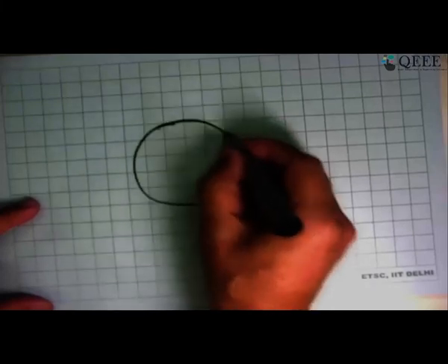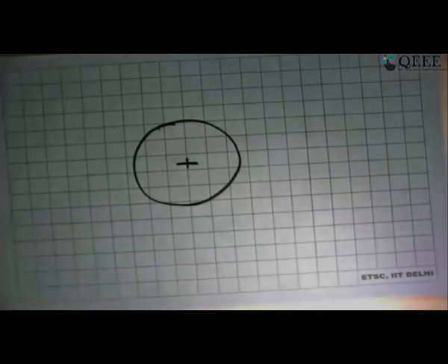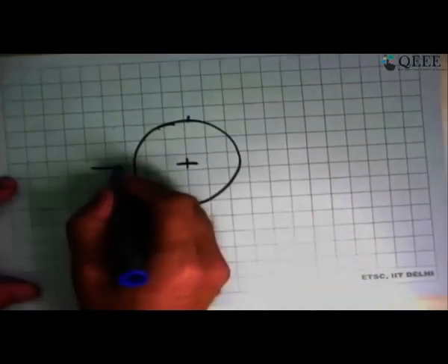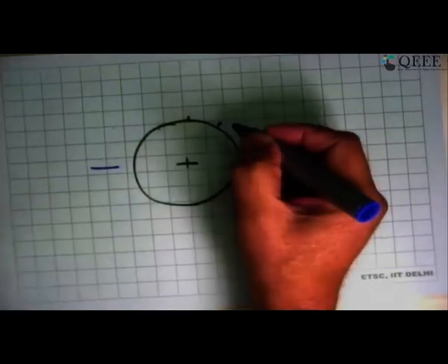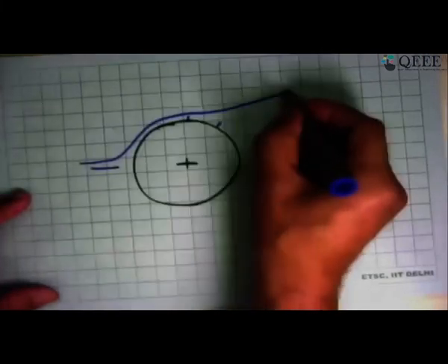Okay, the question is: is the boundary layer separation condition the same for both thermal and hydraulic conditions? Okay, so if you have a flow past, say, a cylinder, and you have separation taking place, say, around 90 degrees in the case of laminar flow, it's about 120 degrees if the flow has become turbulent. So flow has come there and it goes off like that. So here the flow is coming this way. So this is the separation point.